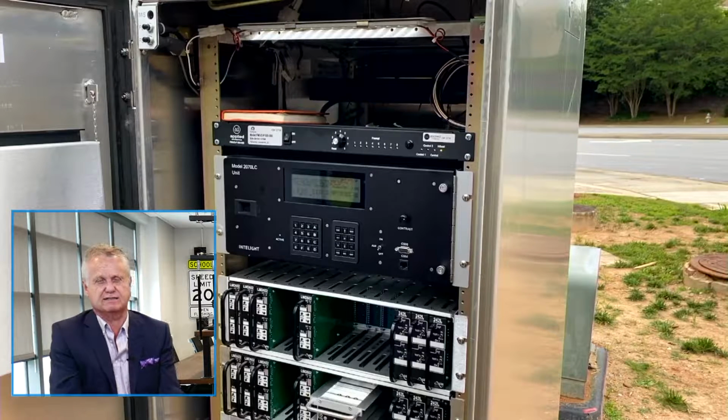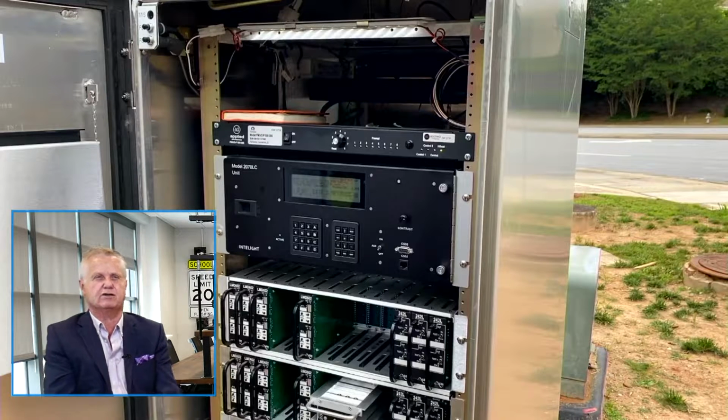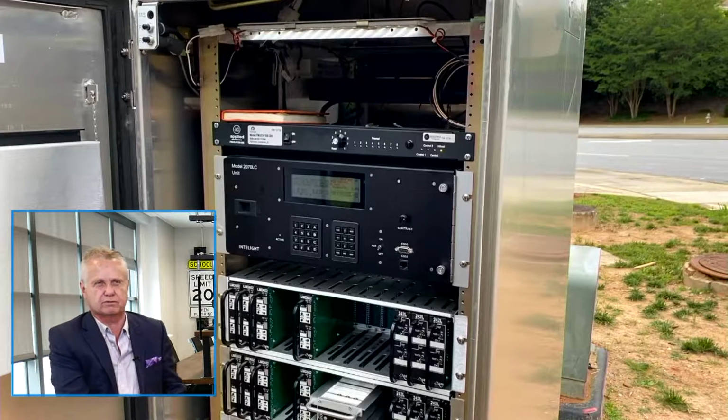The RSU processor does a whole bunch of things, but the key thing it does is run the emergency vehicle preemption rules based on the signals received by the radios. And it's got some test buttons and so forth, so you can actually test the interface with the traffic controller to make sure that when you're calling preempt number 1, 2, 3, or 4, whatever your rule calls for, the traffic controller behaves correctly.